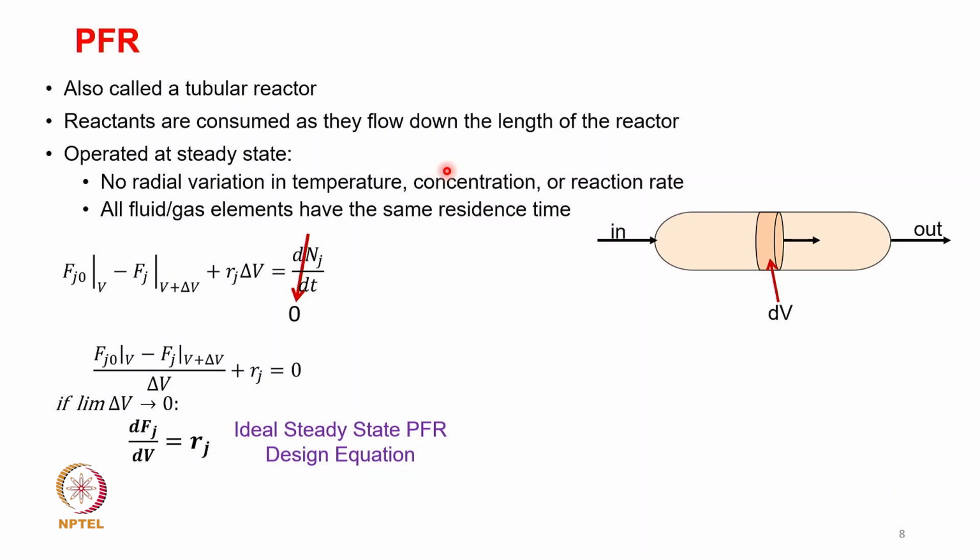Like our CSTR, the PFR is also operated at steady state, and the key aspect is that there is no radial variation: no radial variation of temperature, concentration, or reaction rate. Of course, it may vary axially. All fluid elements would have the same residence time.